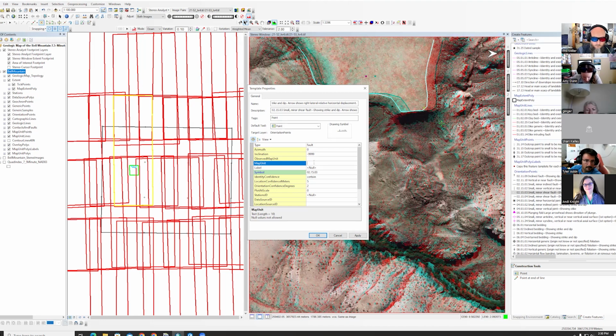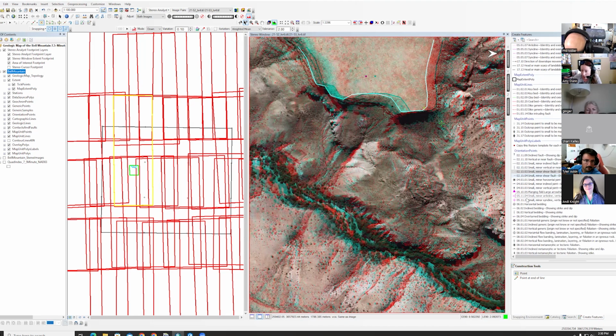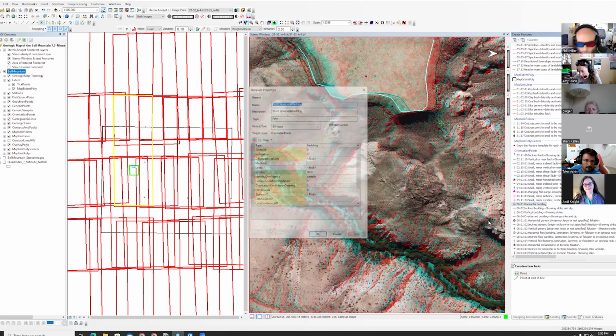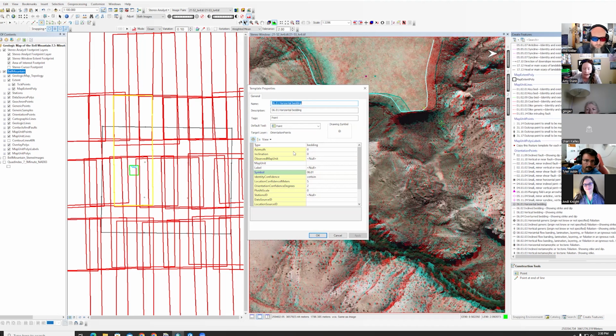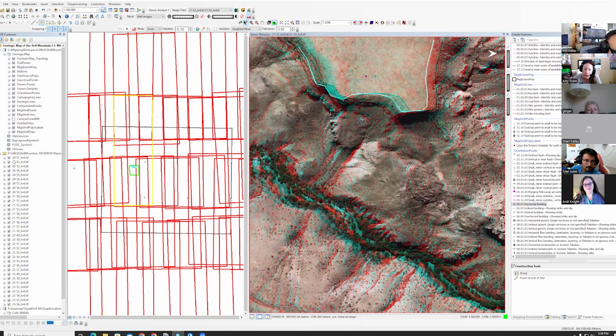The other thing we've updated is in orientation points. I've updated all of the symbology so that the symbols rotate off the azimuth field, and the azimuth field can now be strike, trend, or dip direction. There's also a cartographic option because some of our points are just rotated for cartographic purposes and not actually measured. But you can go into the FGDC symbols table, if Phil will open that one.